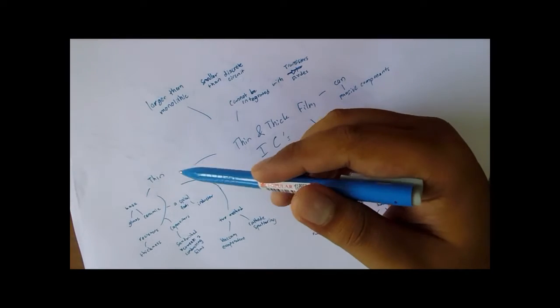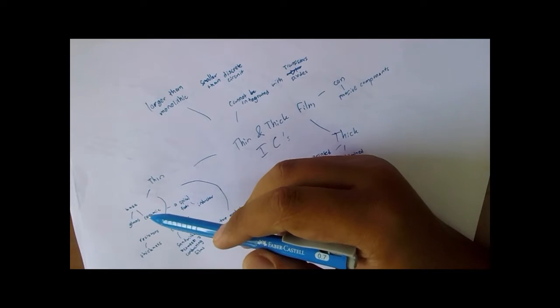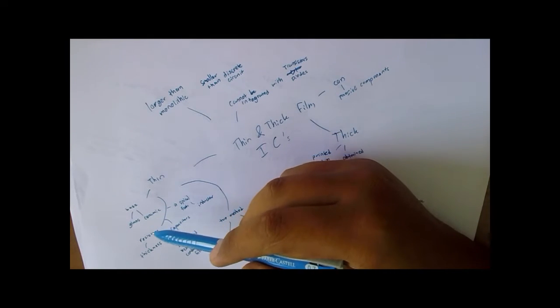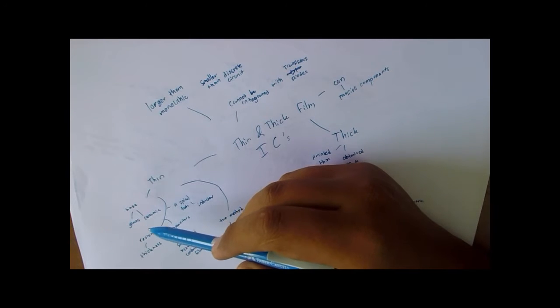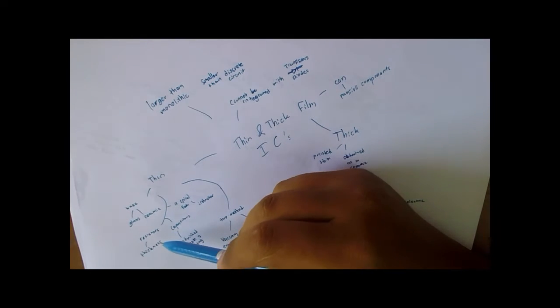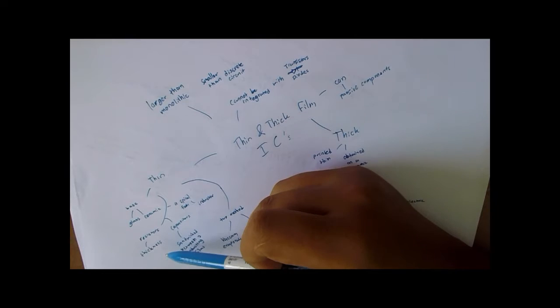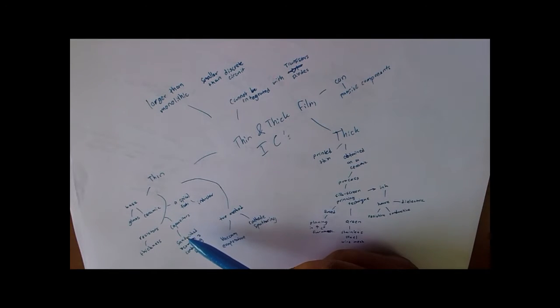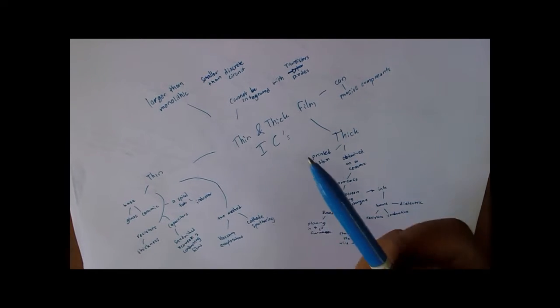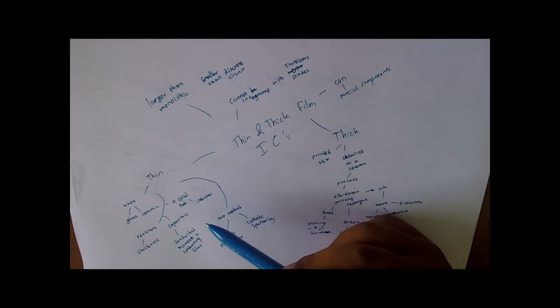Thin film ICs, which is usually the best, use a material such as glass or ceramic. Resistors are fabricated by controlling the width and thickness of the film and by using different materials selected for their resistivity. For capacitors, a film of insulating oxide is sandwiched between two conducting films. A spiral form of film is deposited on the IC to create an inductor.